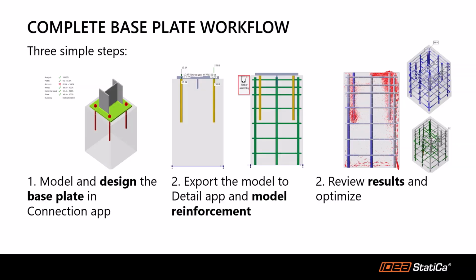Once you have the base plate and anchor designed, you can export the model geometry, all the elements, like the anchors or shear lugs, and loads or load combinations to the detail application. In detail application, you will need to model the reinforcement and run the analysis. Finally, you can review results and design or optimize the concrete reinforcement.